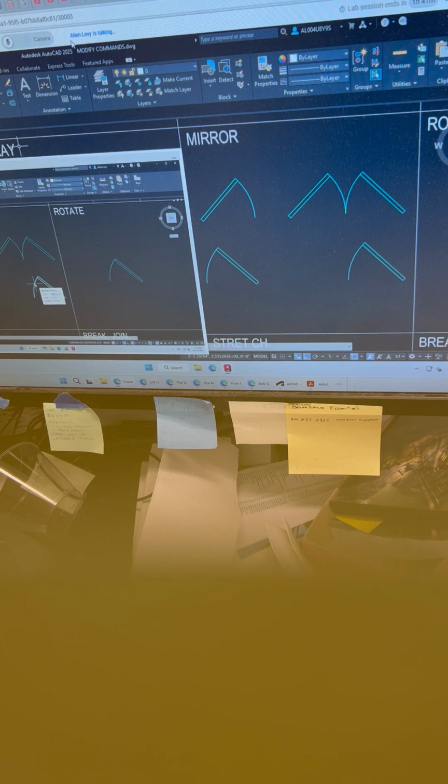So here, let's do it this way. Select the object first. So go ahead and select this block. Start the mirror command. Pick the end point of the arc as the start point of your mirror line. And then draw a nice straight line either up or down. And pick a point. Now this time when it says erase source objects, you can go ahead and hit enter